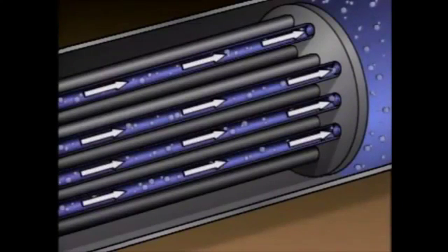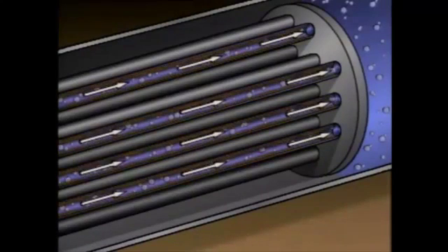Gases dissolved in the fluids that flow through a heat exchanger can also cause fouling. For example, some gases react with the metal inside a unit to cause a type of corrosion. The corrosion forms a layer that acts as an insulator, just like impurities or algae.